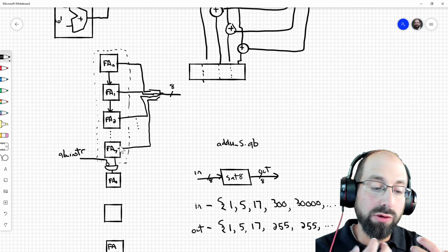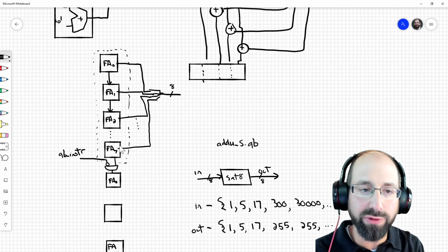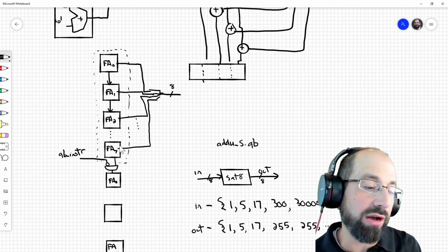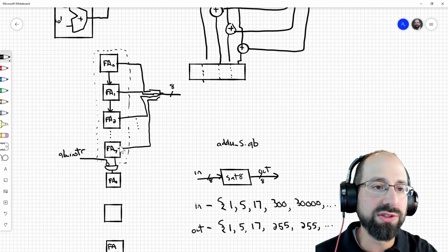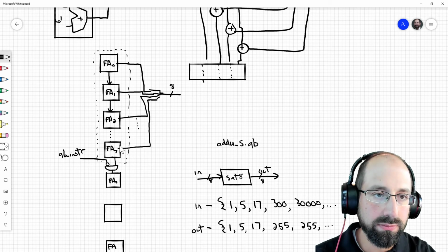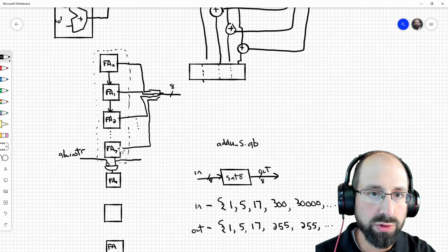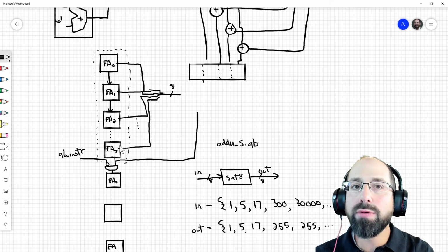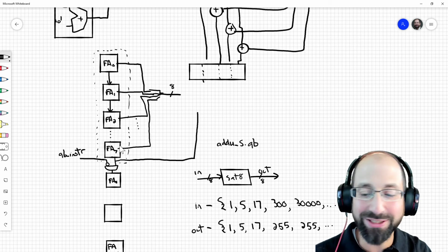So the only scenario we care about for that saturating addition for the individual bytes at a time is whether or not there was actually a final carryout, whether or not the result really did need that 9th bit to be correct, to fit within that value. And now we're back to add a mux, which is always correct.